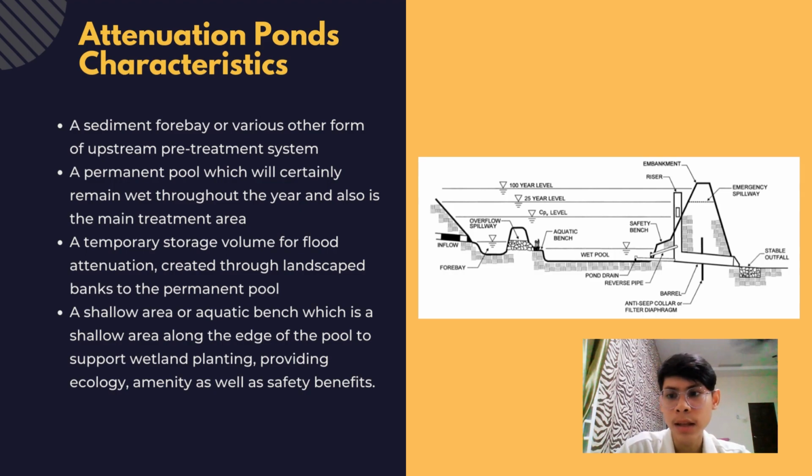Additional pond design features should include an emergency spillway for safe overflow when storage capacity is surpassed, maintenance access, a safety bench, as well as appropriate landscaping.